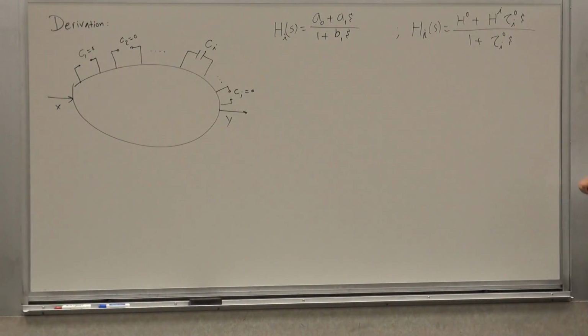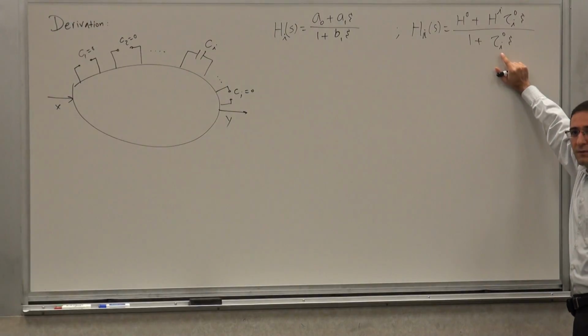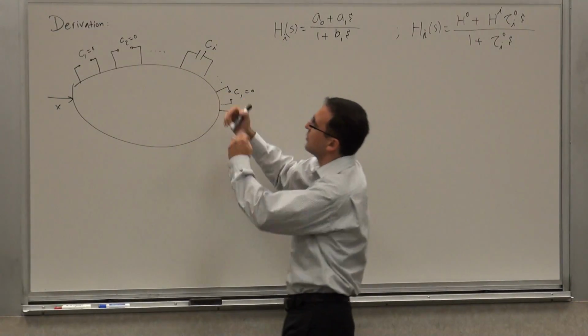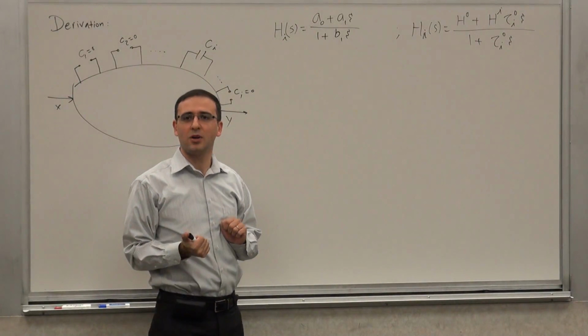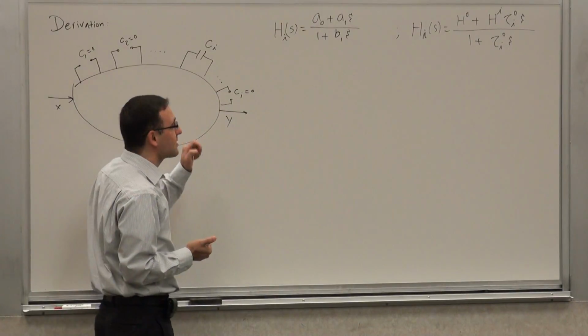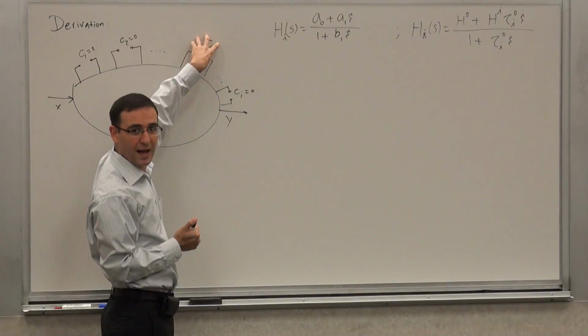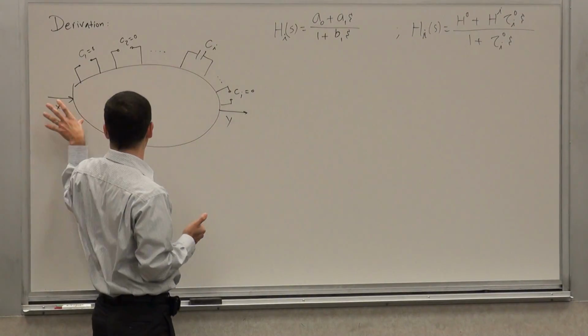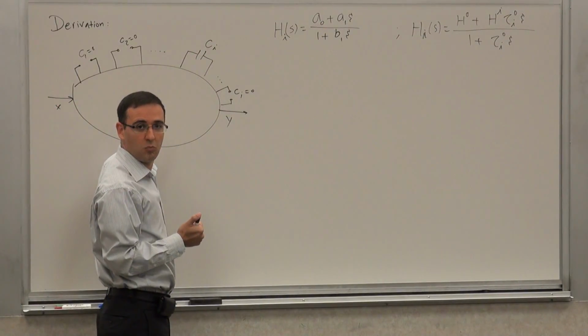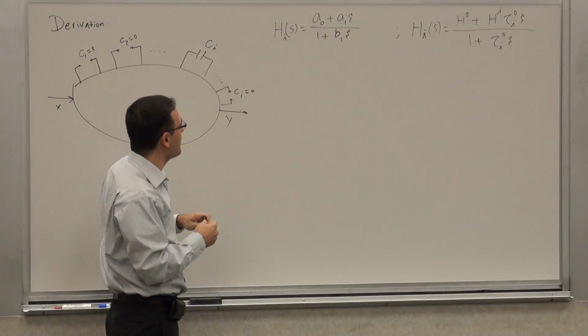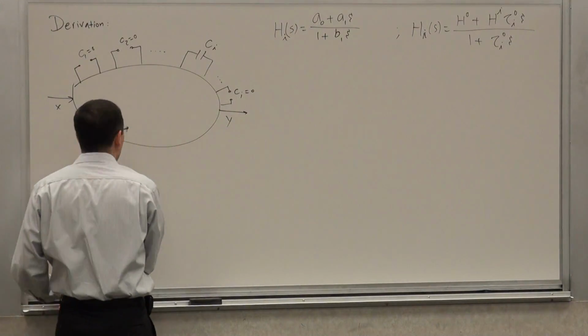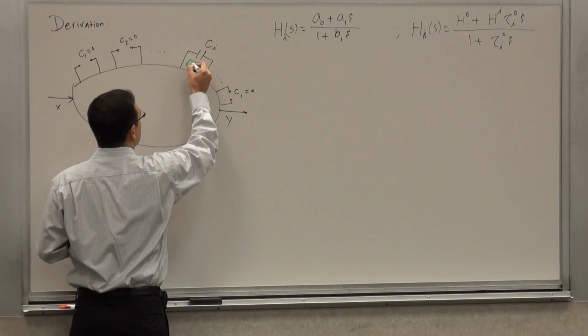Think about it. What I'm saying is that the transfer function of this system, well, it's a first order system. How do we determine its transfer function? What is the time constant of this system? The time constant of this system is the resistance seen by this guy times this capacitance when sources are off. But that resistance is by definition the zero value resistance.